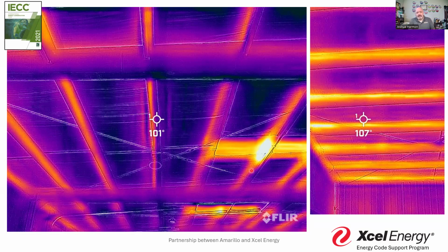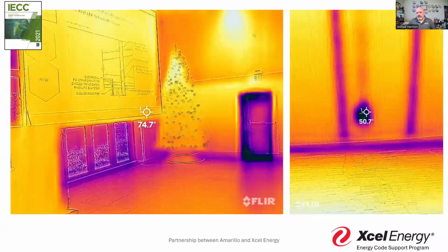I know a contractor who builds steel frame houses. They're literally metal buildings, and they just put up the insulation and then they move in. So again, we want to make sure we're paying attention to that kind of thermal bridging. And this is a good resource. Now, again, I suggest this for contractors just as much as inspectors. But having this technology, having this alternative means in your mind is a way to make sure that the building is going to be efficient and effective when it comes to how it operates.